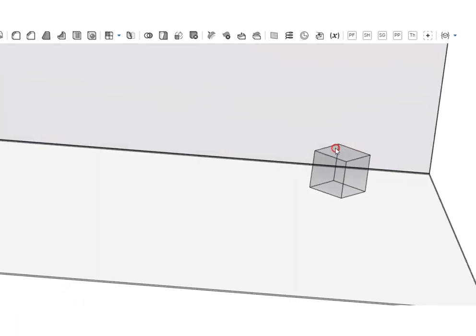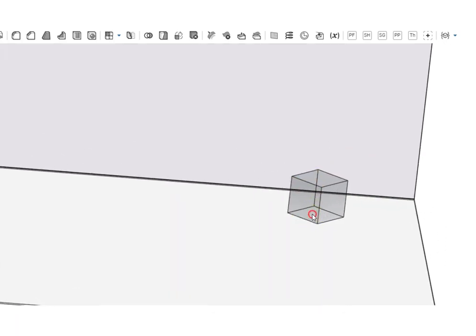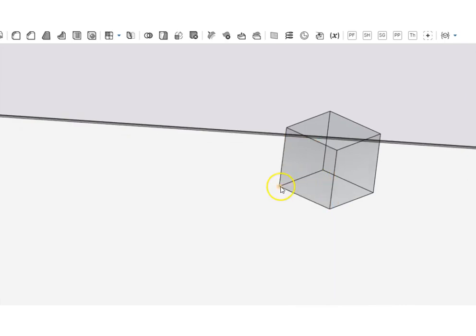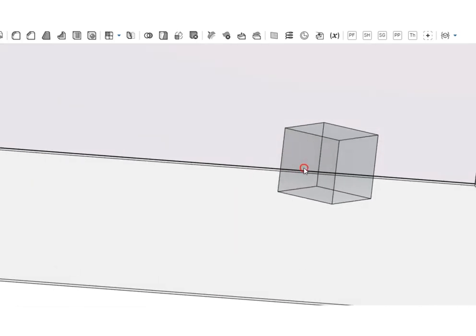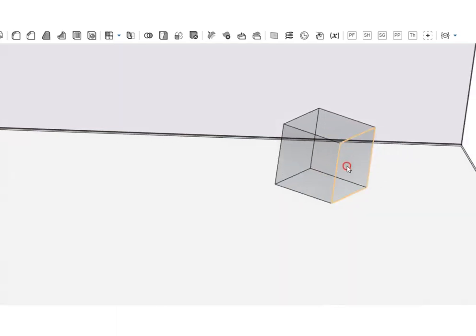Before making the body diagonal perpendicular, first of all, we need to know that this body diagonal, let us take this body diagonal, the line joining this point and this point, is now currently at an inclined condition. So the steps would be to, first of all, rotate this body diagonal so that it is parallel to the XY line, or parallel to the horizontal plane first. And then if you rotate it 90 degrees, now it will become perpendicular to the vertical plane.